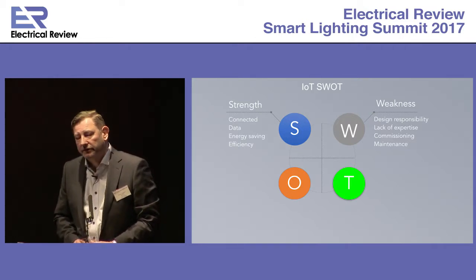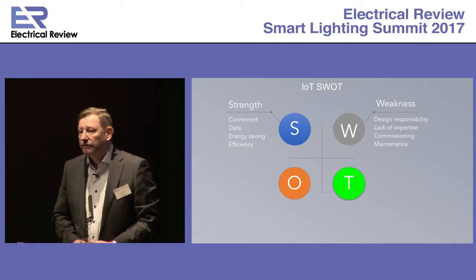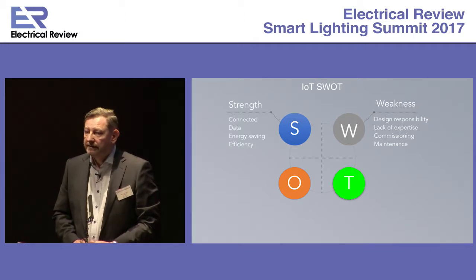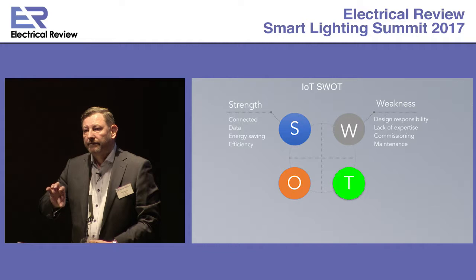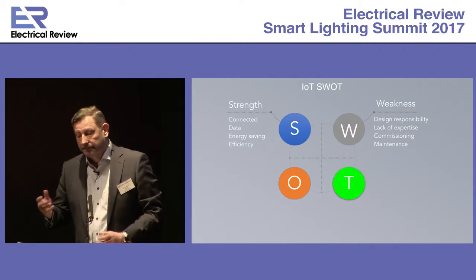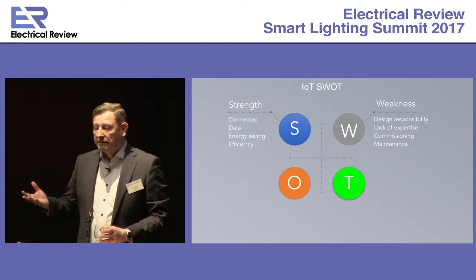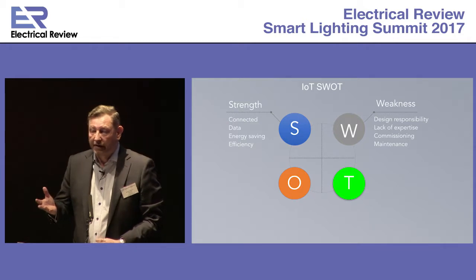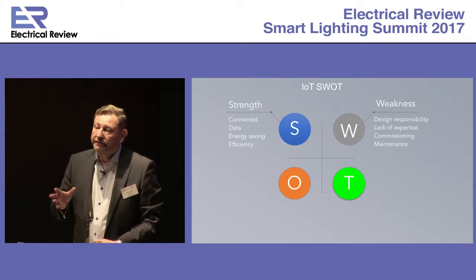When you get a specification from a mechanical electrical engineer or design engineer, he will say, I want lighting controls. But he doesn't determine what that space is and what you do with it. He doesn't determine the usage of that space. And really, if you think about commissioning, we never properly commission lighting management systems. There is a term called POE, which is probably not the term you're thinking of, Power over Ethernet, but post-occupancy evaluation.